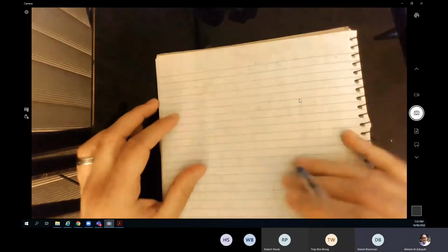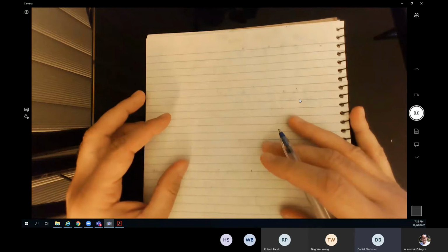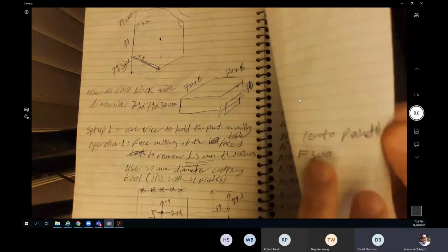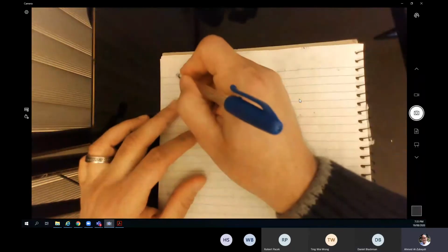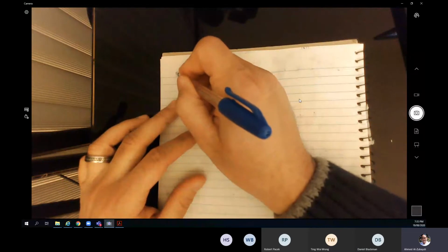So now, did the machine forget the feed rate once you put in the command G00, or does it remember the feed rate? Whatever you write down as a feed rate, if you haven't changed it, the machine keeps using the same value.